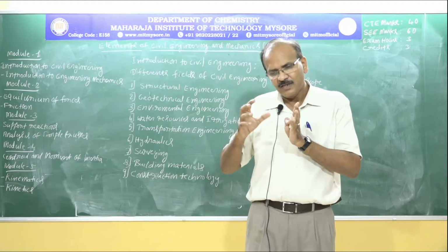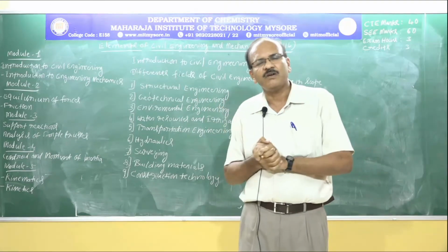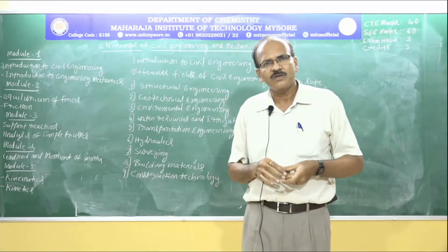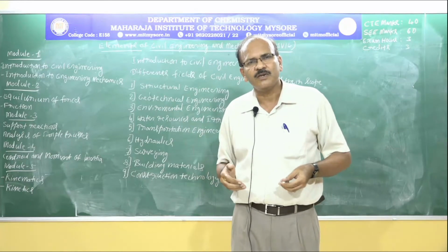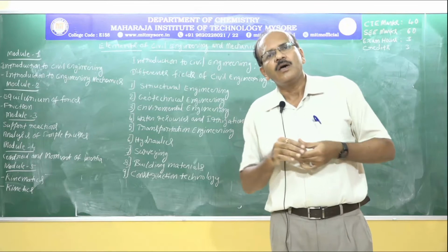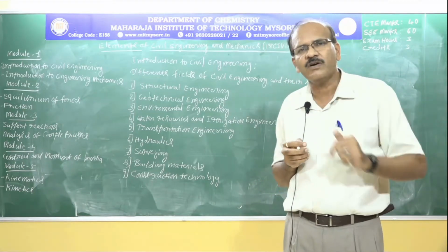So between that you will have a certain quantity of soil per unit weight of soil. Similarly for different sizes. So that is called grain size distribution. Those grain size distributions affect the safe bearing capacity of the soil and also the settlement of the soil.